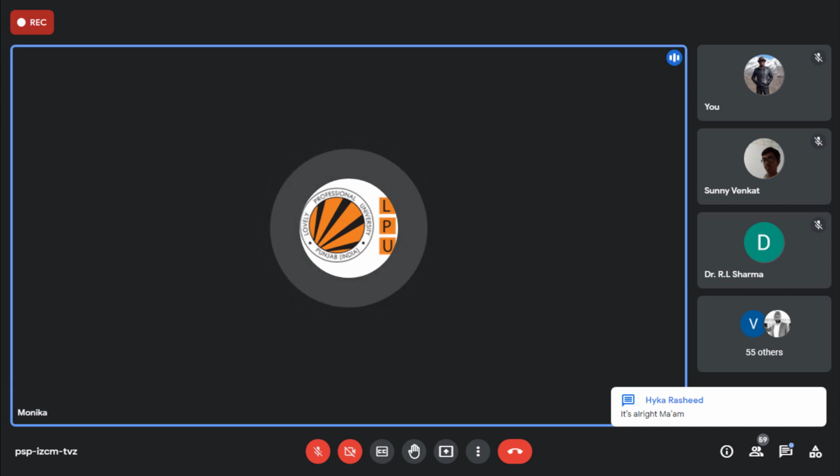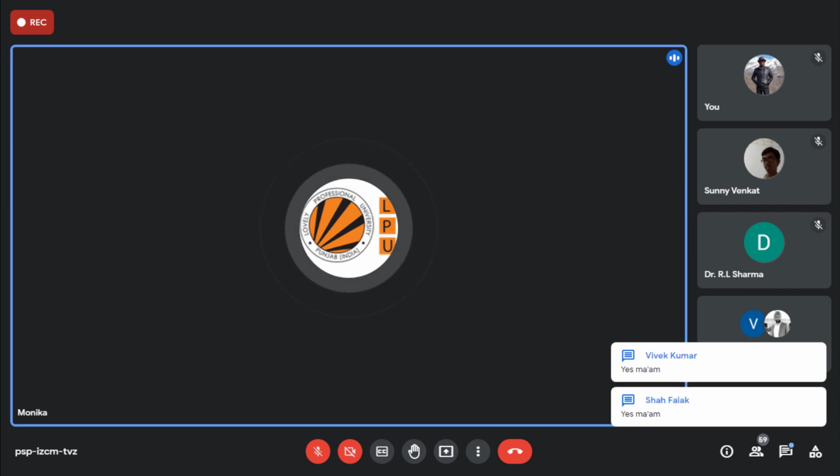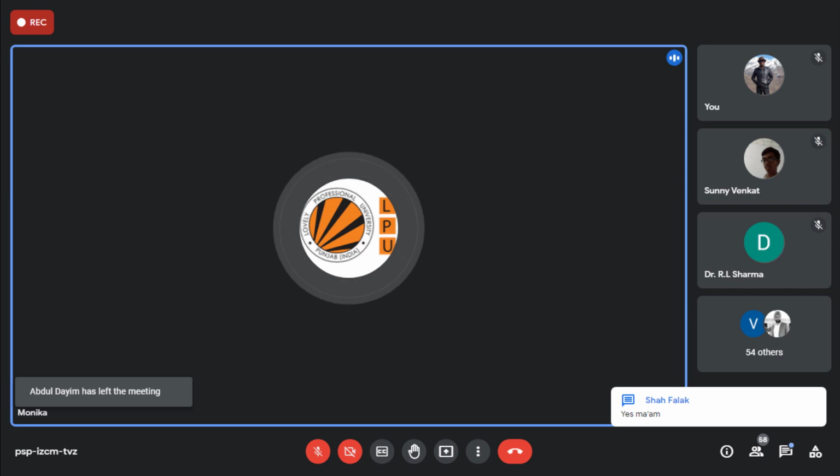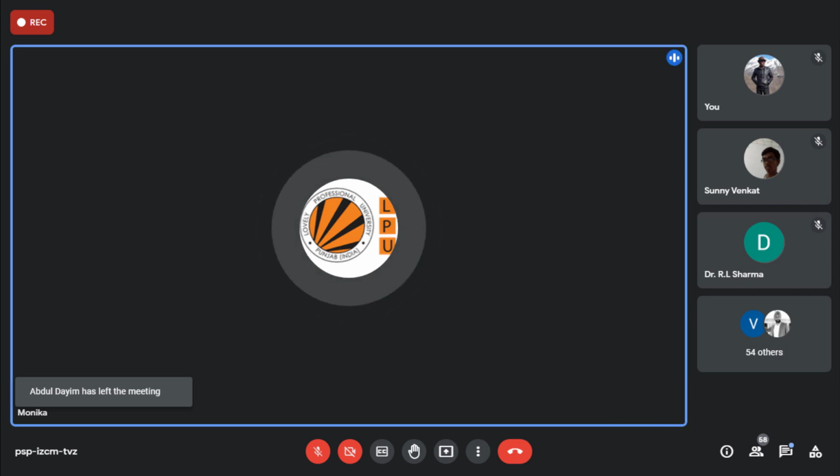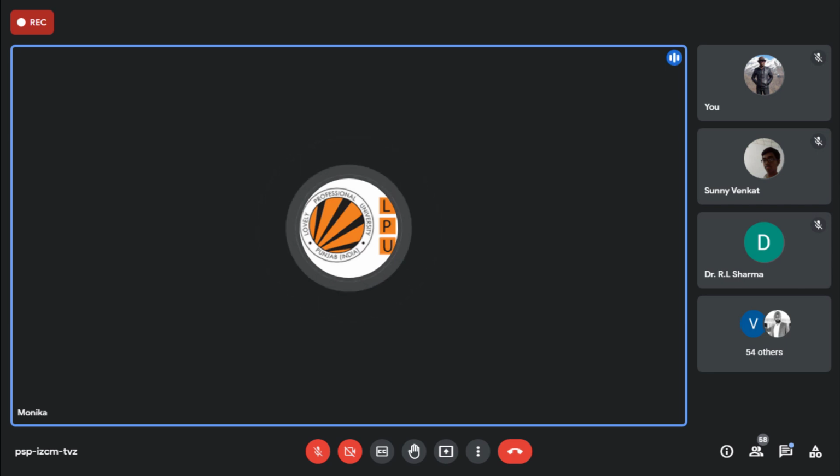Okay. So this is the last slide actually, where I'm telling you that when you show it as two excavators and your budget is only for one excavator, it will show that you are over allocating resources. It is out of your budget. Your requirement is two, but your availability is one. So I hope now it's clear. But see, if you logically link the activities, you have just seen that the same excavator is free after 12 p.m. We can use it in another site. Why write a requirement for another one, right? So in this way, you can reduce the over allocation.